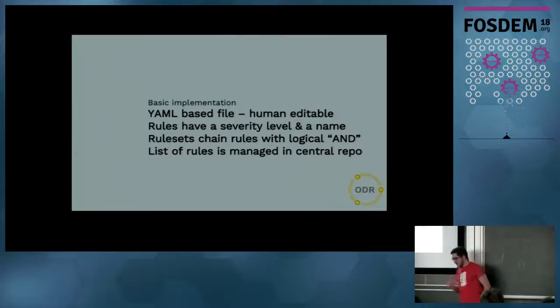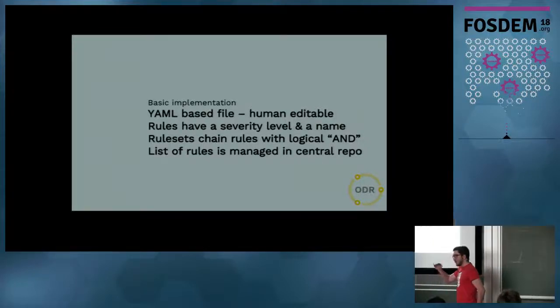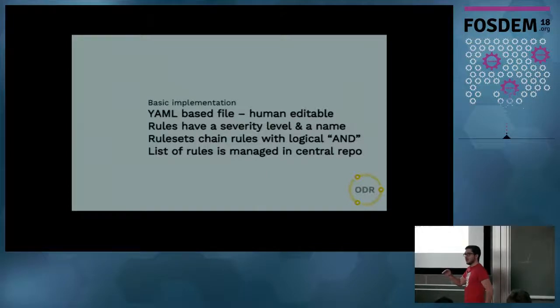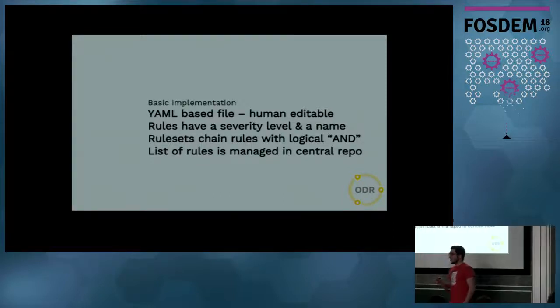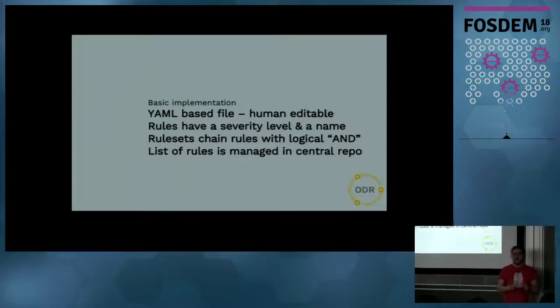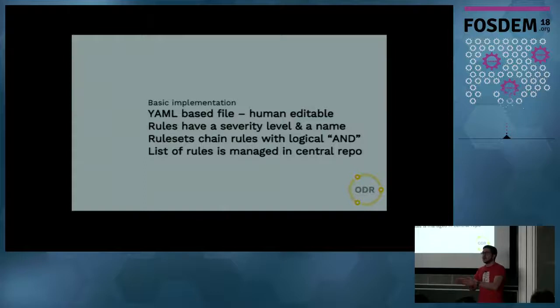Then, every rule in this design rule format has a severity. Because sometimes I just want to remind the engineer that it might not work. Just take it into account. If you accept it, that's fine. So that's a severity of maybe info or warning. But maybe my assembly factory tells me to not place heavy parts on the bottom of the PCB because I'm not able to manufacture this. This is an error, because that will never ever work.